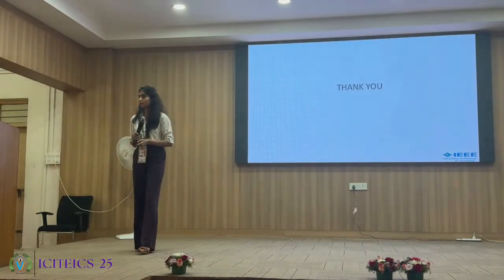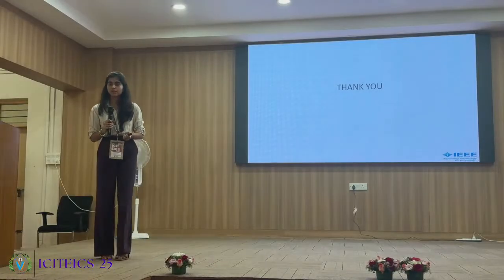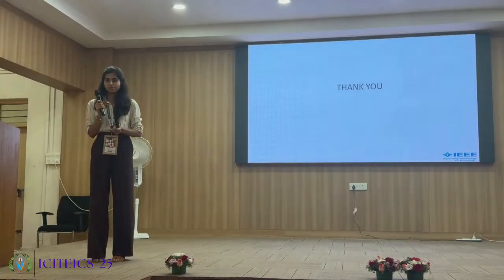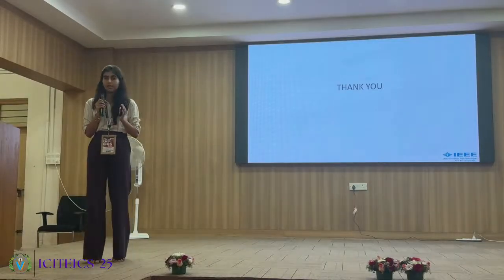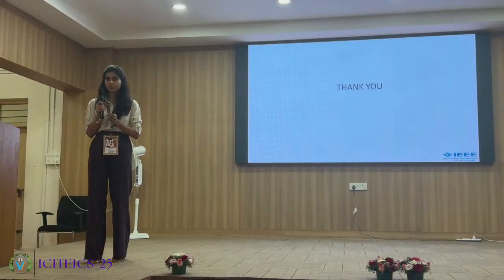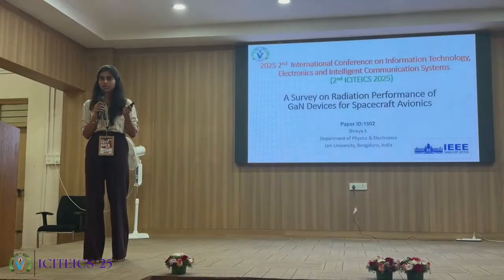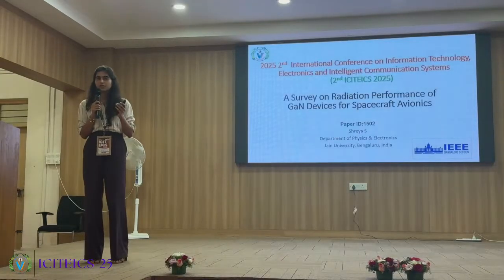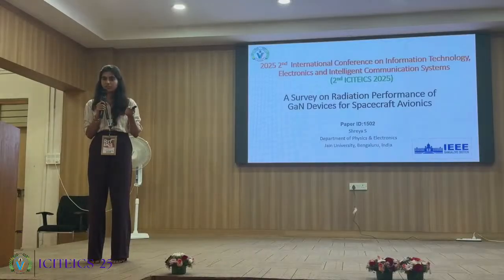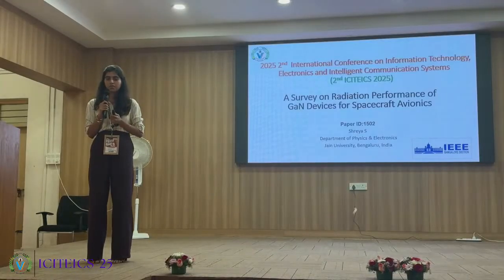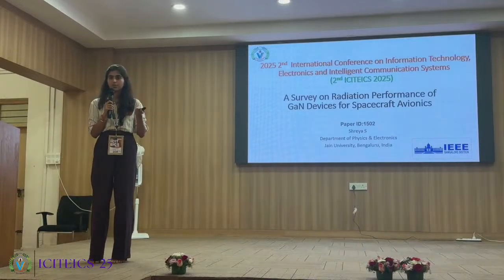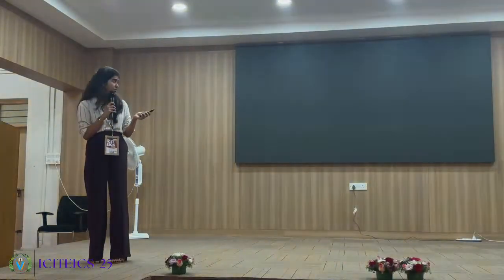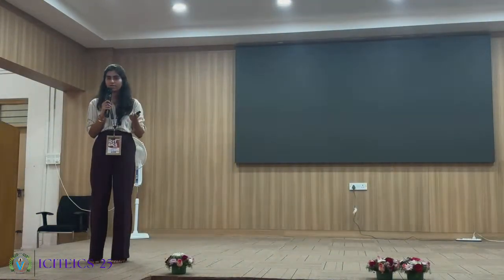How do you find the practical implementation of these things? Okay, so we can really make use of gallium nitride devices in space, especially in space-constrained units, in the DC to DC converters because of their high efficiency and high voltage switching circuits compared to silicon or silicon carbide. These gallium nitride devices will switch or operate comparatively faster.